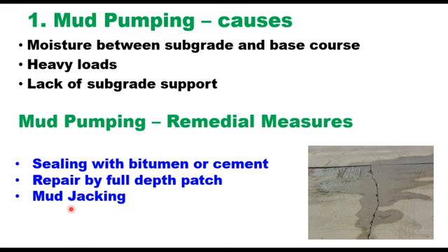Or it can be through mud jacking also. Now, mud jacking is the process of pumping cement slurry under the slab through a hole to lift the slab to its original position or original height.